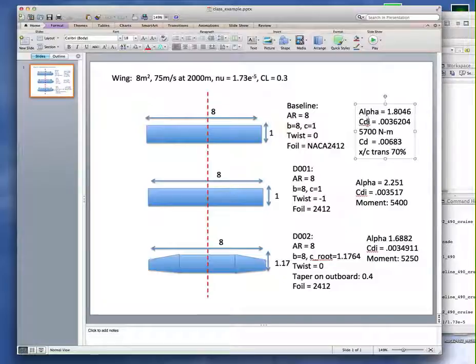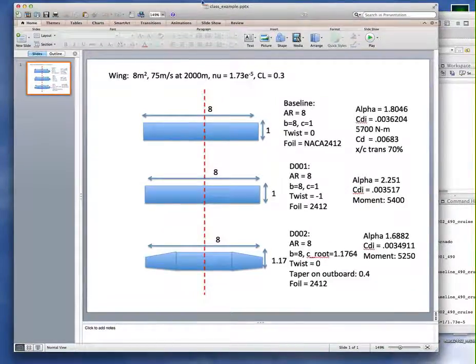And normally design has to be done using a multi-point design, essentially weighing different points. It's got to be able to do this and do this well, and kind of weighing those two factors. We're designing for one design point, and in the world of aerodynamics, you can end up with some weird stuff. So if you get forced in a weird direction, that's fine. Just try to be able to explain it.